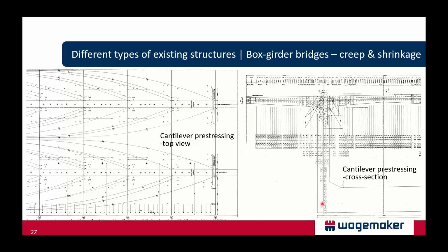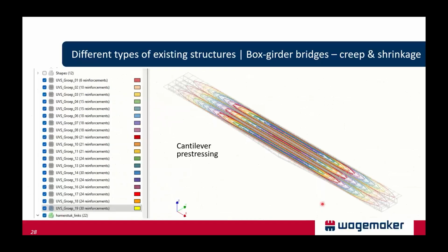So the modeling of the pre-stress is quite some work. We have very detailed archive drawings of the layout of these cables, as well as a lot of cross sections. All this information from the drawings needs to be translated somehow to coordinates, which we did in Excel. And then we used Python to generate the pre-stressing tendons, or in this case, bars in Diana.